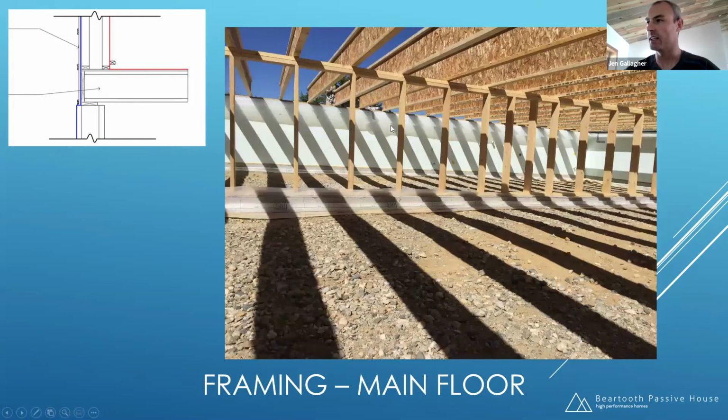That's after we set the floor joists, because we're making sure that poly is completely lining the walls and the floor of this. We got poly that we ran underneath that pony wall before we attached it to the footing. We ran small strips of poly that attached to the top of the stem wall before we ever set our floor trusses, because that would be a lot easier without floor trusses in the way. Crawl space access, Mike, yes, but from the exterior. And I think I might have a picture somewhere along that'll show that.